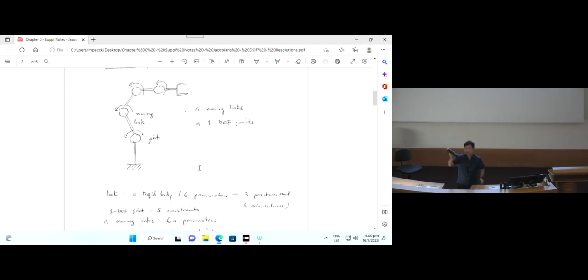So for this object, if I restrict to 1 single degree of freedom, meaning that if I can only turn in this direction, so I can only do a roll. So I can no longer move in x and y as well as z. So the 3 degrees of freedom for the translation are lost. You can only rotate. You can only do a roll. You can't do a pitch, and you cannot rotate along the y and z. So what happened here is you again lost 2 degrees of freedom, so you are only left with 1 degree of freedom.